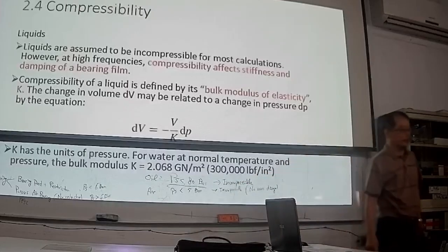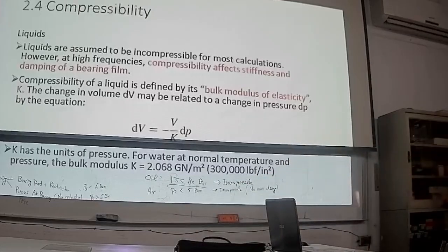Because once you choose a higher supply pressure, the oil becomes compressible, and then you need to choose the oil pipe in different categories. That may increase your cost for your oil pipe.